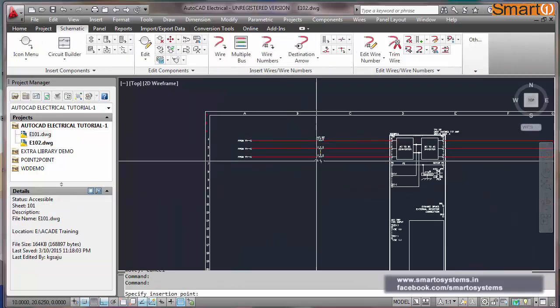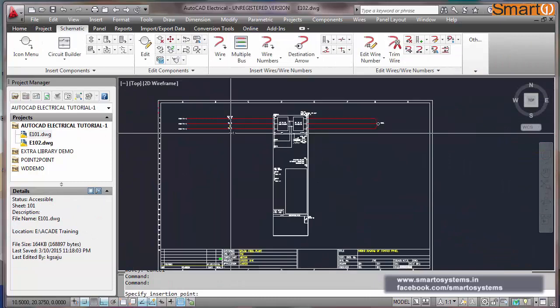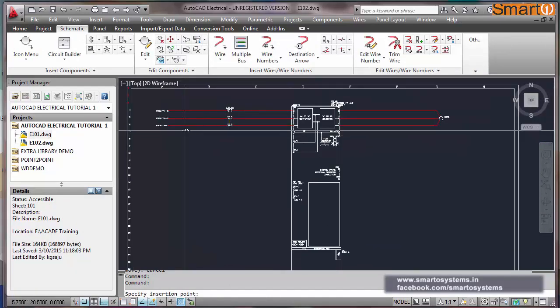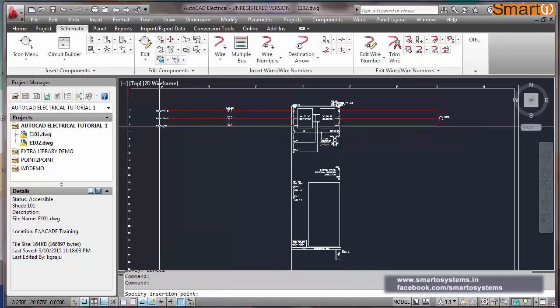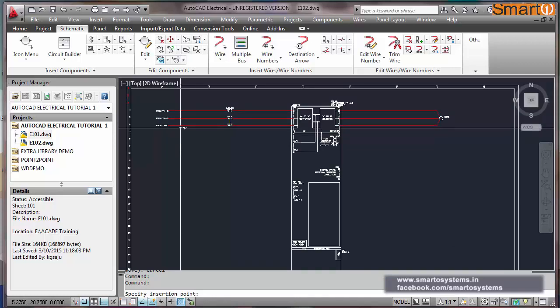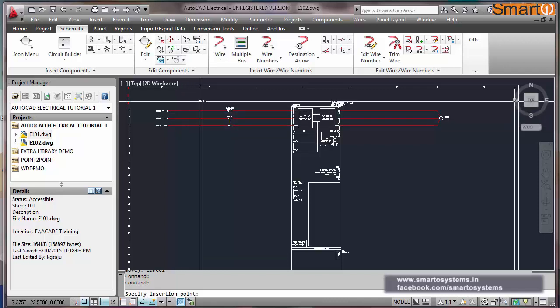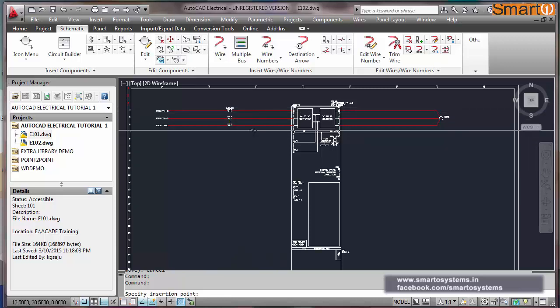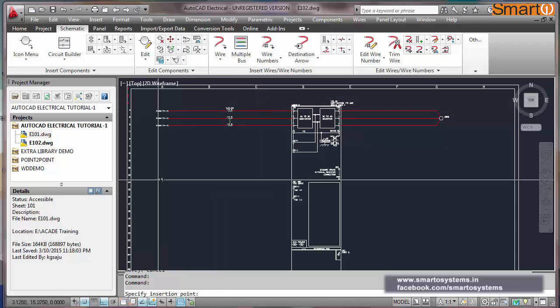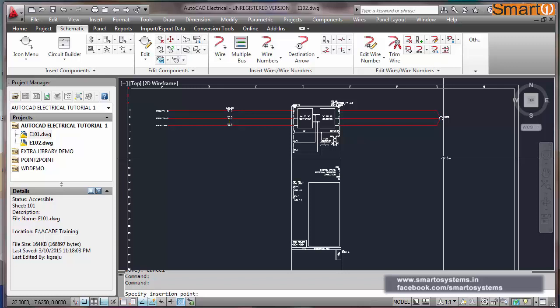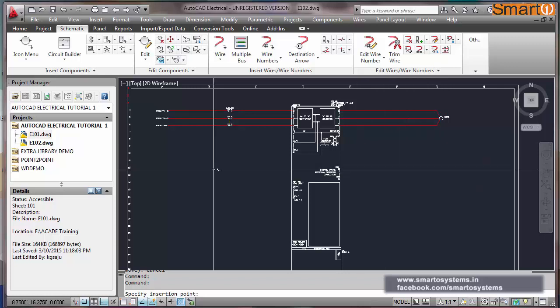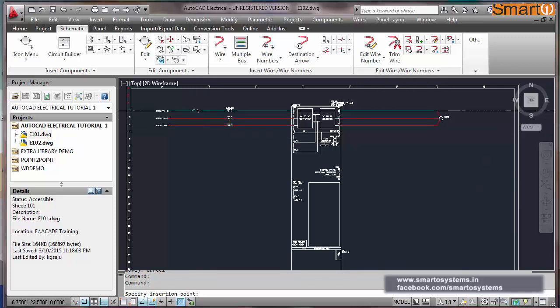And while making the schematic diagram, if you see the flow, I am drawing it from left to right. This is how we make drawings in NEMA. If you are making the drawings in IEC, everything should come from top to bottom. But in this case, it is from left to right. This is the basic difference of standard between IEC and NEMA.